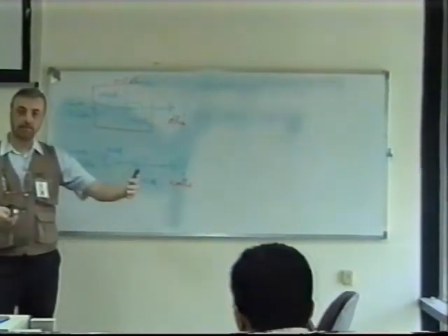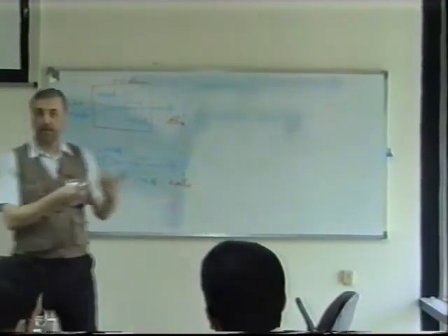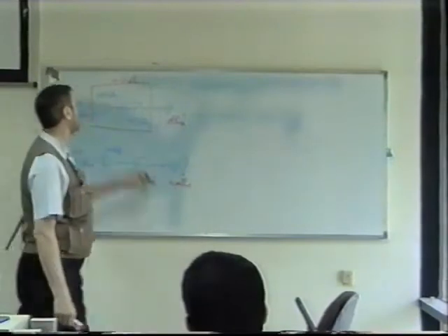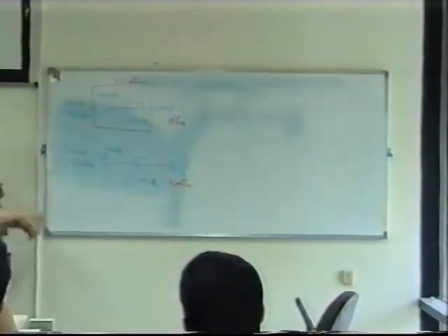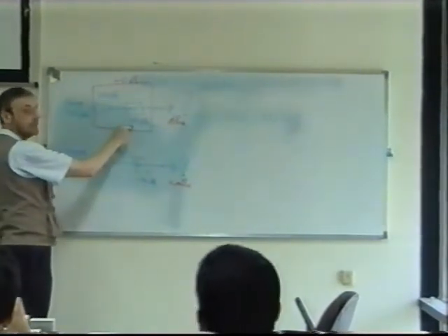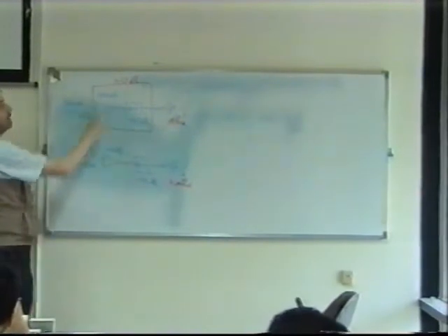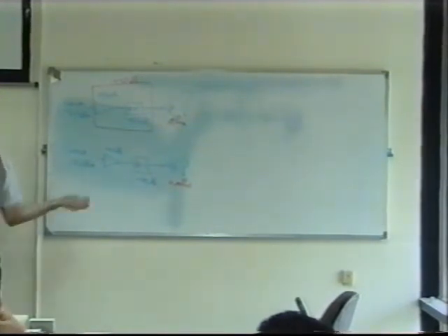Instead of multiplying and dividing, every time we go through an amplifier or an attenuator, we can just add and subtract the dBs. So here we've got 100 dB gain. Here we have minus 60 dBs. 100 dBs is 10 to the power 10, isn't it? Am I right or am I wrong? Yes.